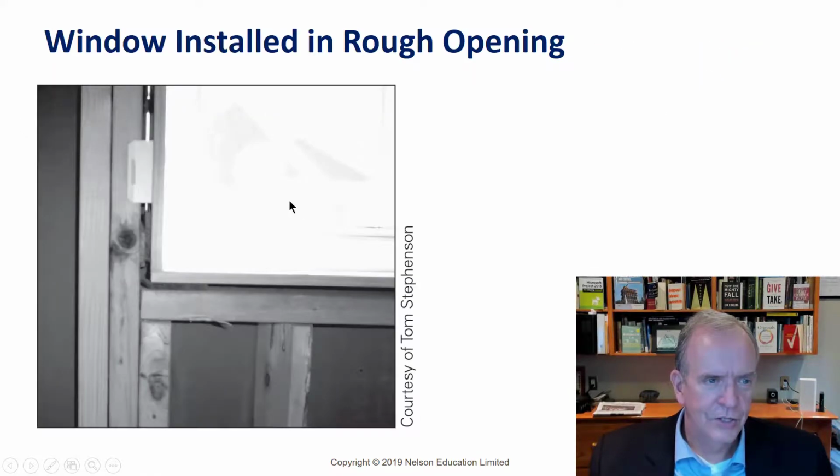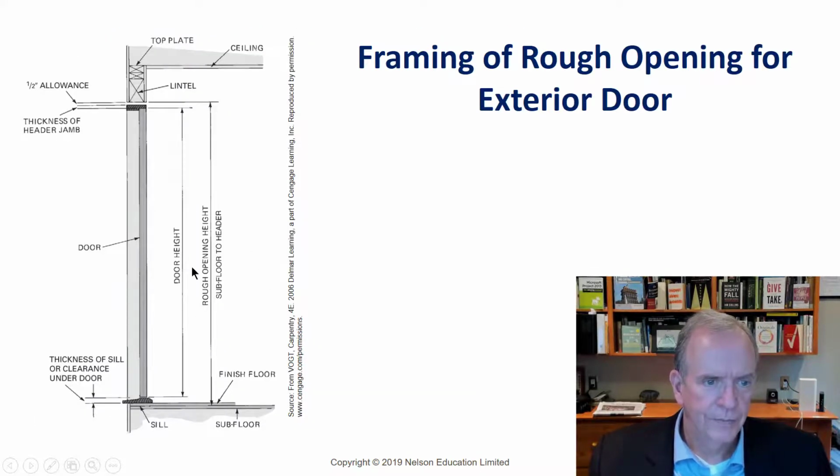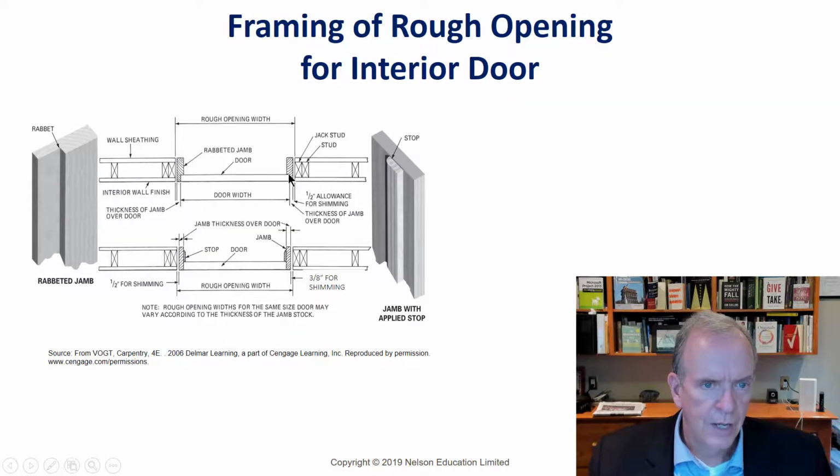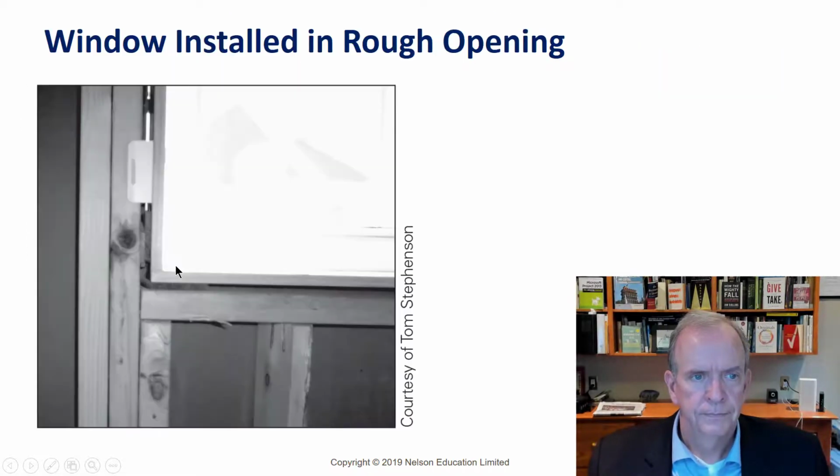And there's your height. You've got to make allowances again to make sure you've got enough room for, if it's an exterior door, the door sill, your hardwood flooring or whatever finished flooring you're putting in there, and that you've got a little bit of extra space here that you can insulate, and then your casing will cover that so you won't see it. The casing's going to cover these spaces afterwards because you're going to put the casing on. The casing's your finished trim that goes around the door. There you can see the shims, there you can see the space. That would then be polyurethane foamed.